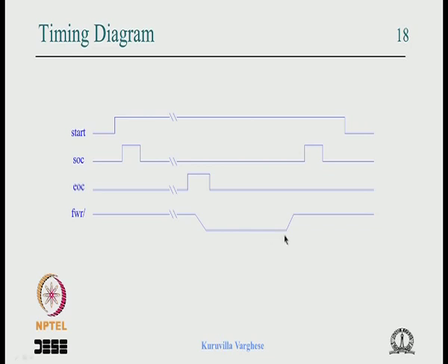Suppose we update this design with a faster FIFO, then the state machine has to change, the controller has to change, maybe only 3 states are required instead of 5. So the question is, can we remove this timing from the implicit states we add and move it elsewhere? A subsystem that keeps track of the width of the timing pulse would be ideal, because if there is a change in the width of the pulse we can modify that subsystem easily. Maybe there is some flexibility to do that.